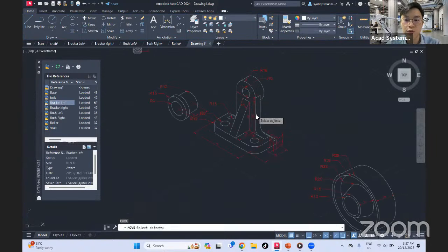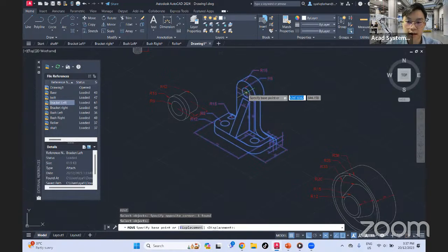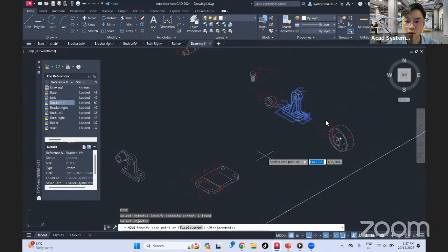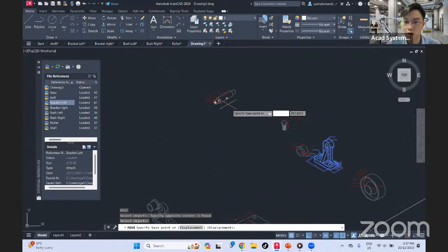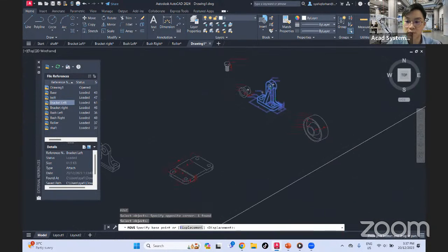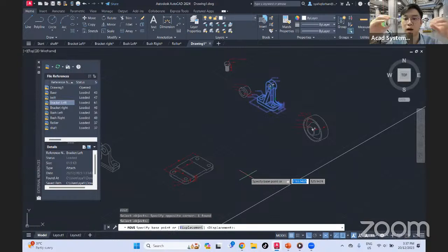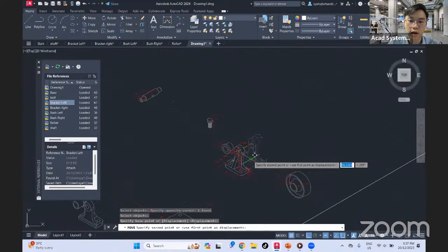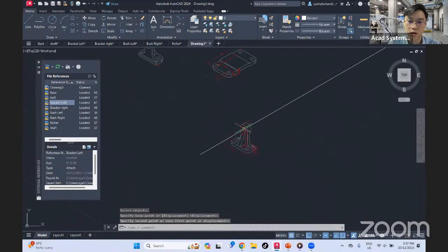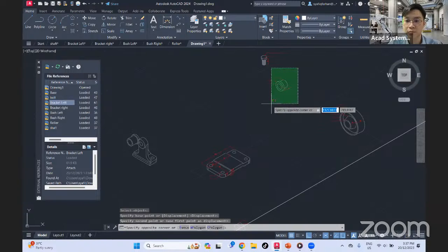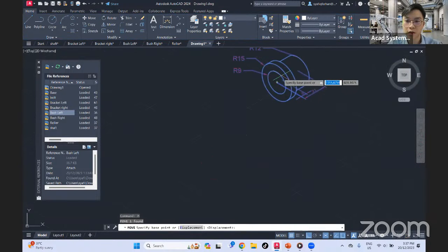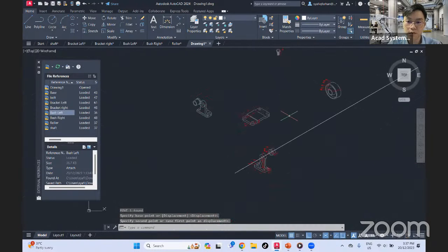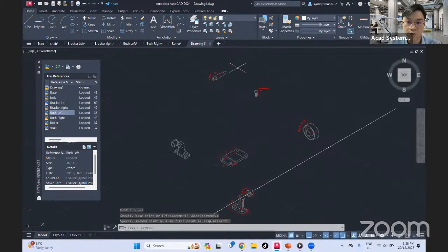And basically it's just moving your objects and selecting the base point. Example, this is a belt roller and all of these brackets, the holes, they will enter into the shaft over here. So I will use this middle line here as the movement where they will explode out from the middle. So I will use this hole as my base point and snap onto the reference line that I've just created. So similar on this side here, this is the base point and move it over here. And then next will be the shaft.